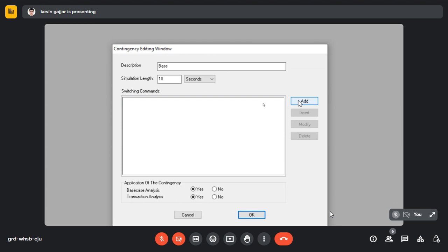Then in the add tab, now in 10 seconds, if we do not add anything, then it will take the default values. Default values means that to perform any simulation, what is required is the time step and the numerical integration method. Those 2 we have to give. Right now there are some default parameters, but we can change them and give whatever settings or parameters we like. So let's give some time step and integration method here, and then we'll see the default values as well.